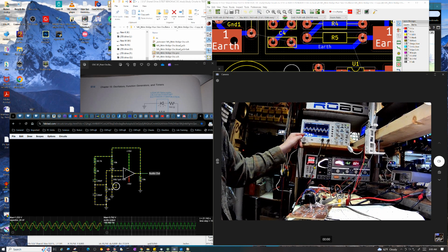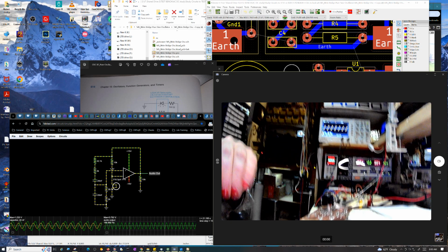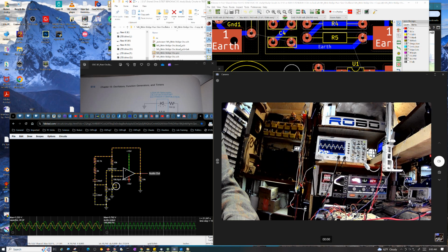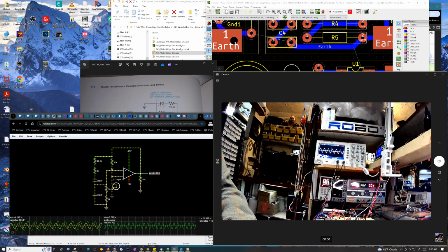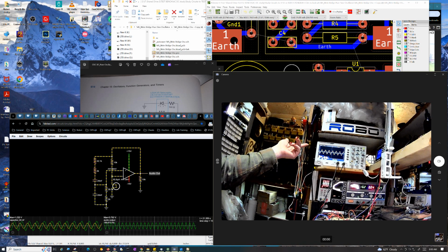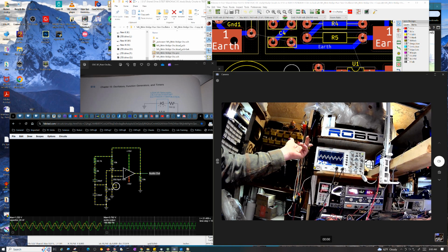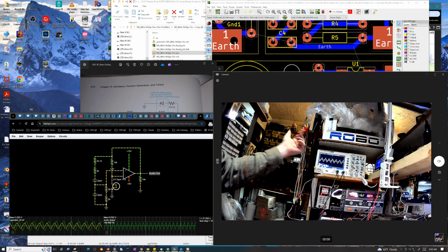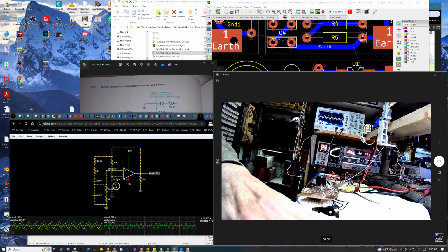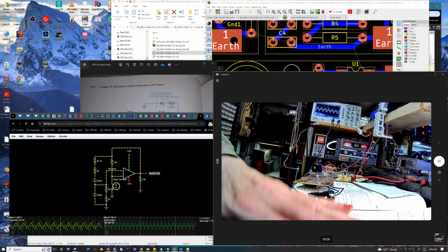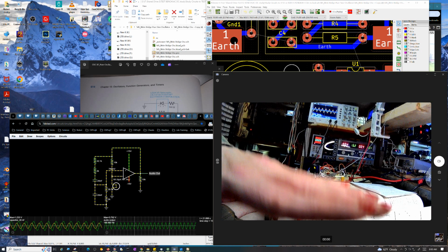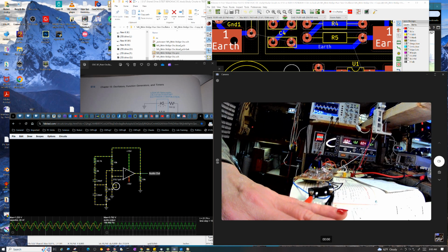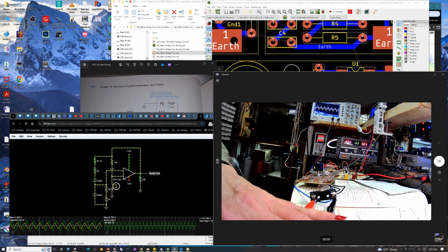Okay, it's 450 kilohertz right now, and it's 388 kilohertz right now. If you put this into a nonlinear mixer with a reference signal, you could actually make a theremin of sorts with this. It's not super sensitive, but I'll bet you could accentuate that somehow.